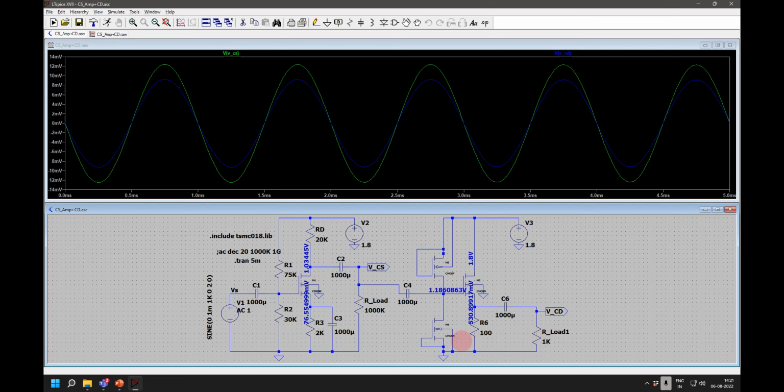Is it okay? But sir, in the sub-threshold region, if the current is in picoampere, with process and temperature this current will change drastically, right? Which one? These currents? Yes. See, I have just given an example where you can do that. Generally, for all analog circuits, we will learn about current mirrors next, after differential amplifiers. We use a reference voltage and constant current biasing to keep it stable. I have just given you one option. I have deliberately put this so that such options are available to you.